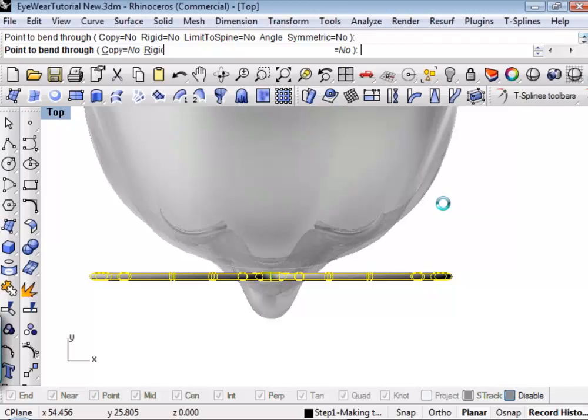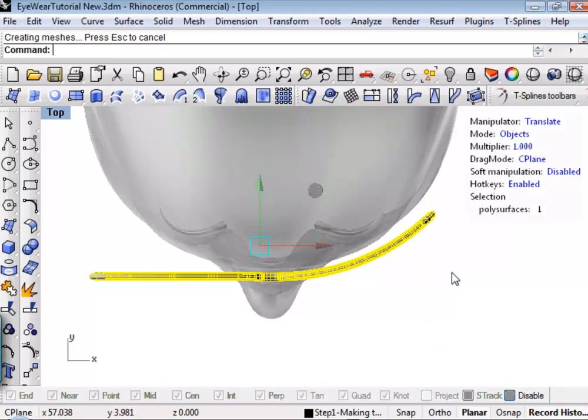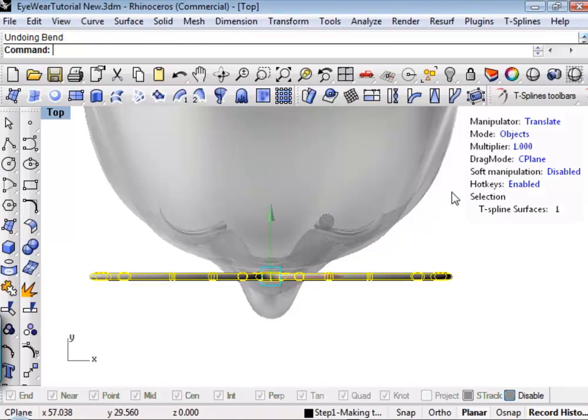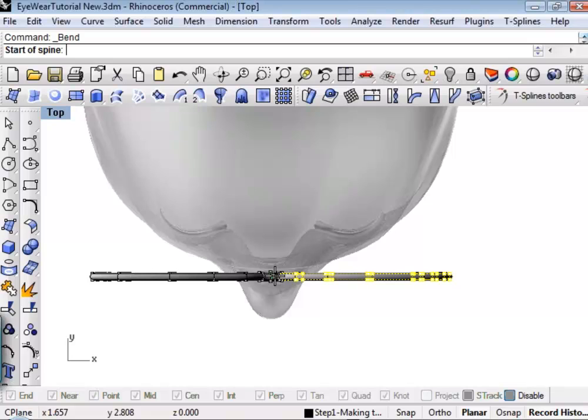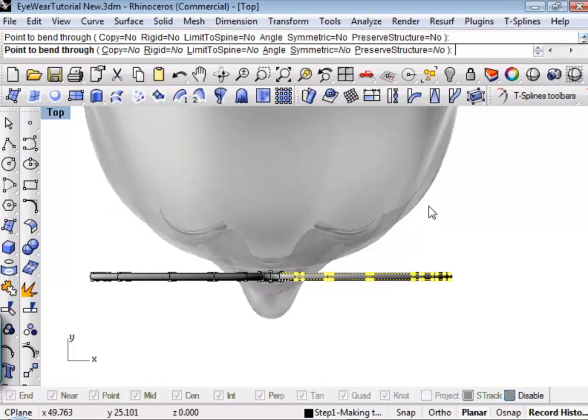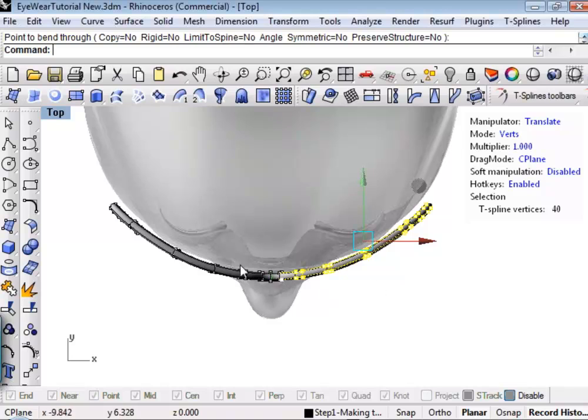it's going to convert to a Rhino object. You'll notice here it's a polysurface. I don't want that, so I'm going to undo that. I'm going to go to my vertex level. I'm going to pick the vertexes that I want to modify, and then I'm going to use the Rhino bend deformer. I love this. And I'm just going to bend this model. Super controllable, super efficient, super clean. And obviously, since the model's symmetrical, once I bent it, it mirrored it across the line of symmetry.